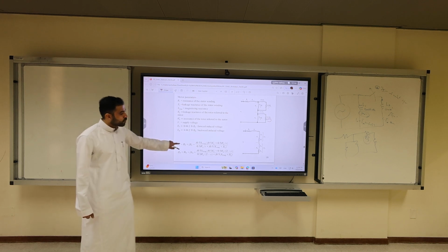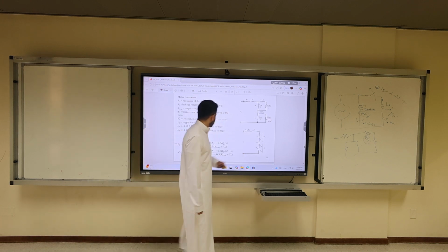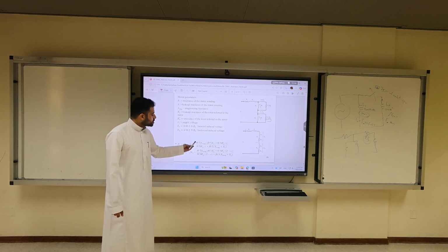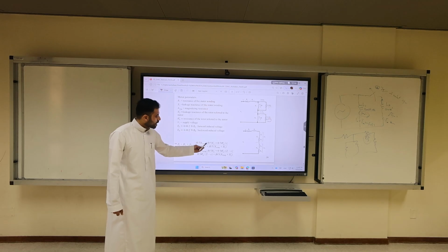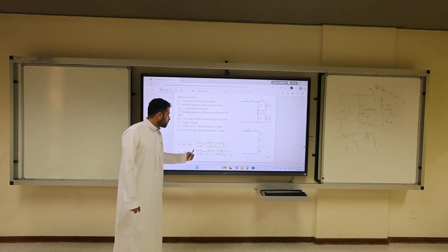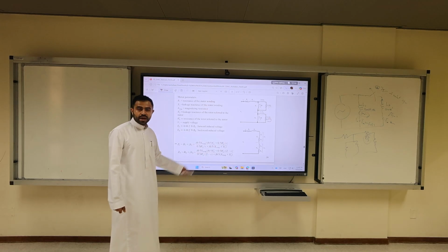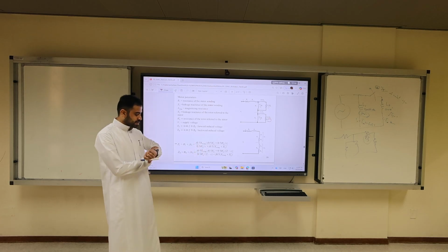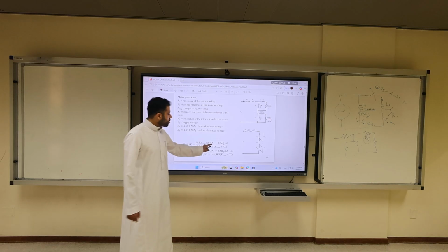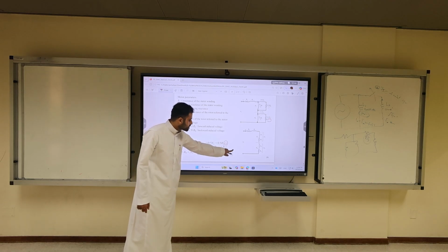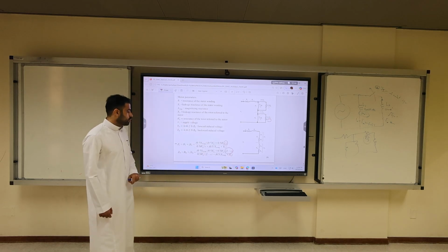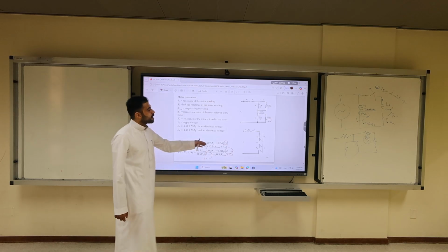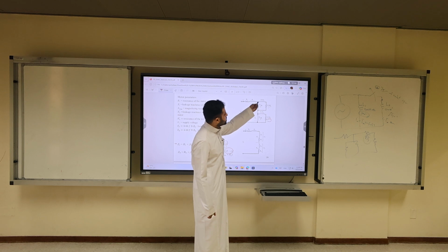We have Z forward, this is Z forward, this is Z backward. So Z forward, if you do the math, it's j0.5 Xmax times this number over this number. And this is clearly formula sheet friendly. We will solve an example next lecture. But what do you notice here? This is a function of S, this is a function of 2 minus S. But this is the parallel combination of this and that.